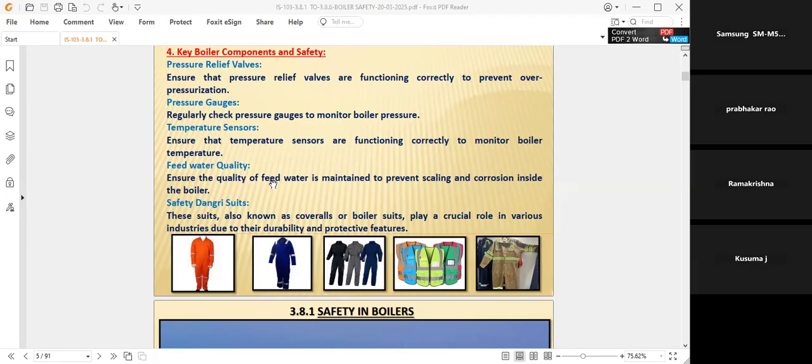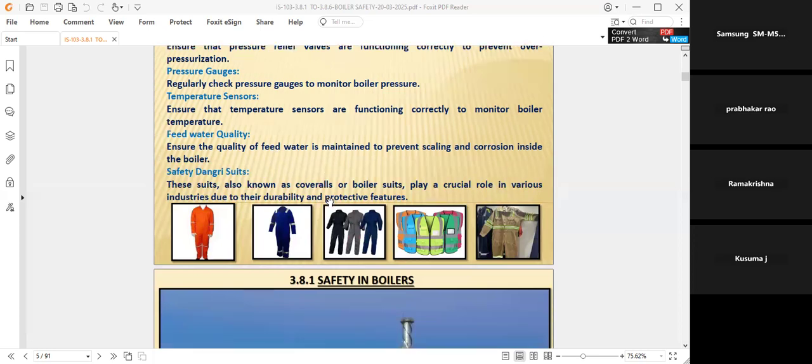If the specifications are not maintained, definitely the tubes inside the boiler will have scaling and corrosion, and thereby erosion as well as leaks will be observed. Therefore, a lot of time is lost in shutdowns, and a lot of financial commitment is also lost, because due to that, other departments also need to shut down. Sometimes the turbine depends on your boiler, meaning HP steam, so the turbine also needs to be shut down. That's why it's a very important area.